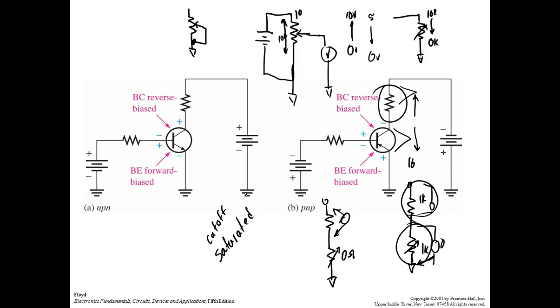So a transistor will drop a voltage when it's saturated, but it's usually going to be less than 1 volt. And then when you cut it off, your transistor is going to drop the applied voltage. We can't measure the leakage current through that thing, as long as we operate it below breakover. Are we okay? Yes or no?